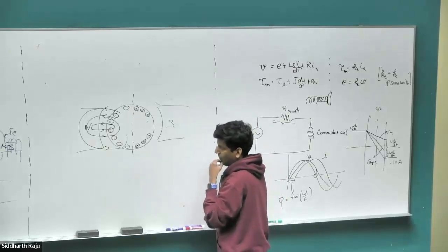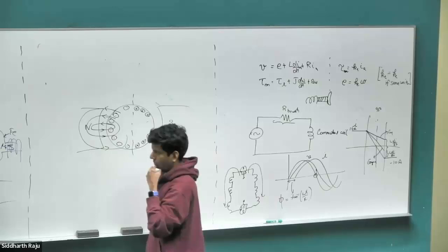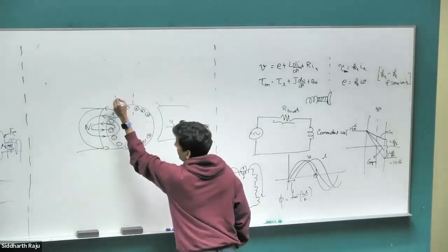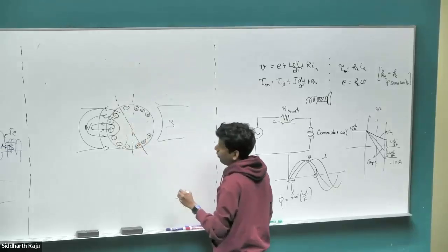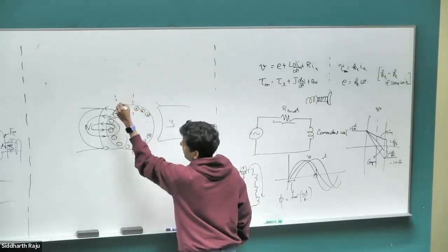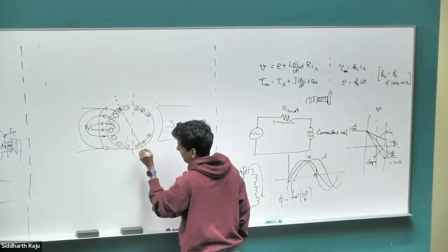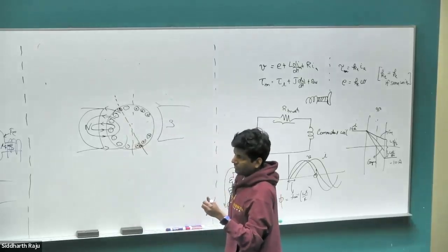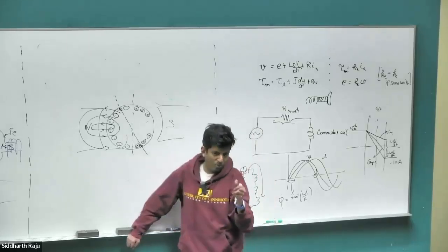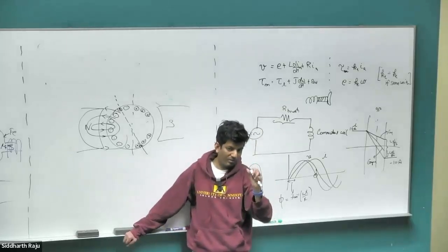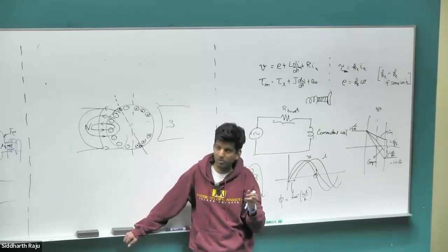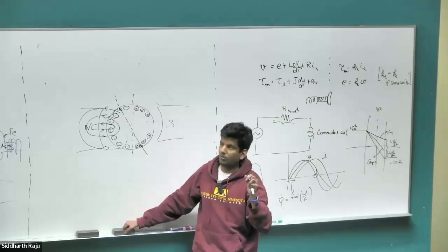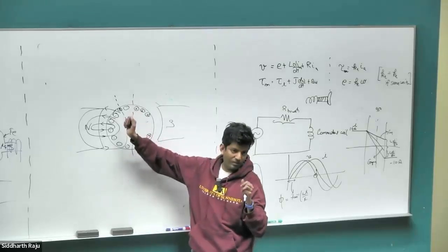Now, if we have this, when we assemble these motors, there are two problems. Either we can intentionally phase shift the axis so that the commutator segment is no longer at the 90-degree point, but at some angle slightly shifted away intentionally, or it can be an unintentional consequence as well. As the rotor rotates, the brush position can shift a little bit. Or even during assembly, it is not particularly possible for large motors to make sure that the angle at which the brush segment sits is exactly 90 degrees.